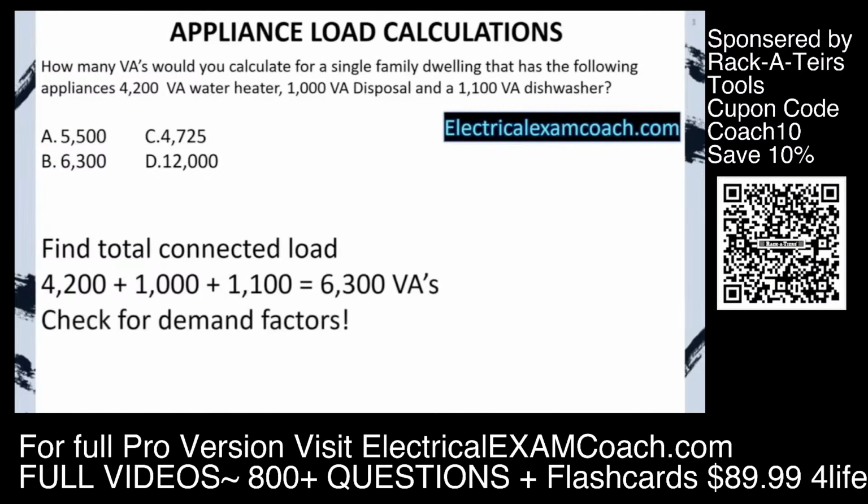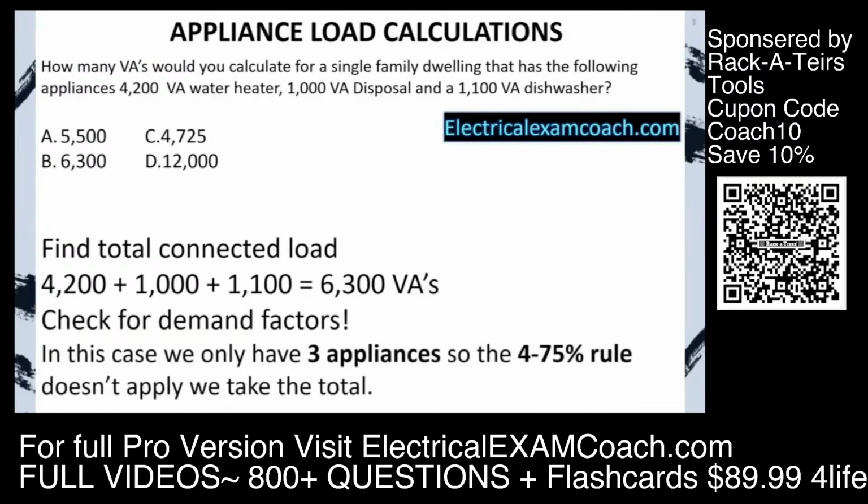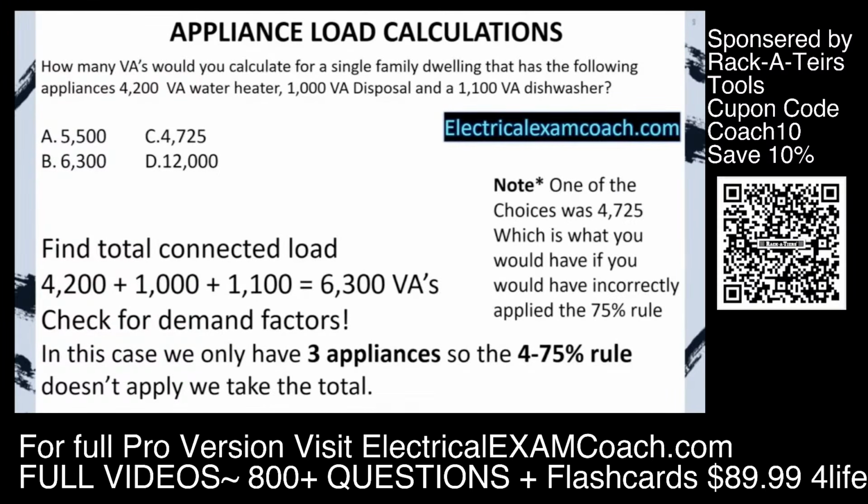Now, we check for demand factors. In this case, we only have 3 appliances, so the 4 or more 75% rule does not apply, and all we have to do is take our total. I do want to note that one of the 4 choices was as if you had incorrectly applied the 75% rule. In this case, because we only have 3, we don't apply any demand factor at all, and we take the total connected load at 6,300.